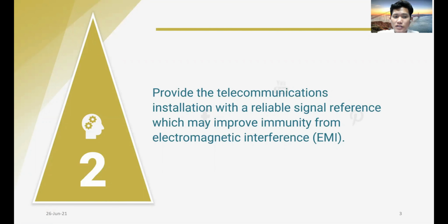If these different areas are not well equipotential, harsh transient currents could appear, such as lightning or mains power fault, causing a high voltage potential difference between the interconnected equipment. Communication interfaces like the board or the module could be disturbed or damaged by this common mode voltage.